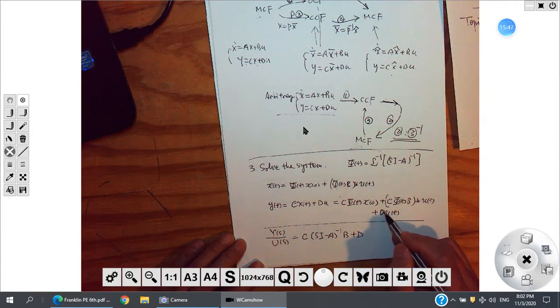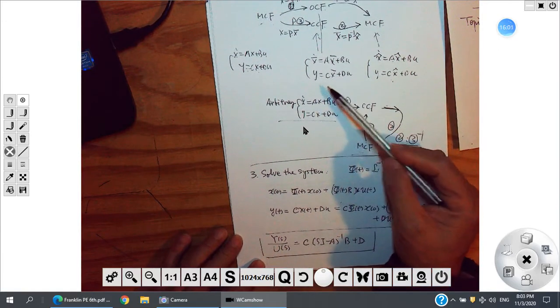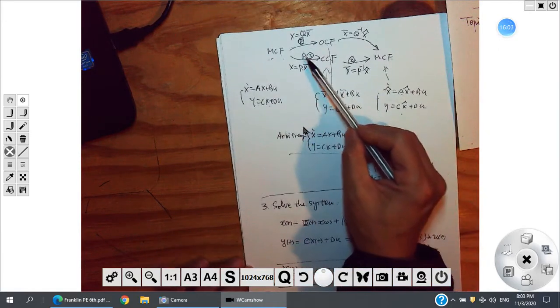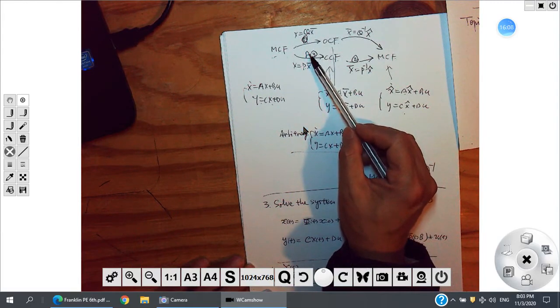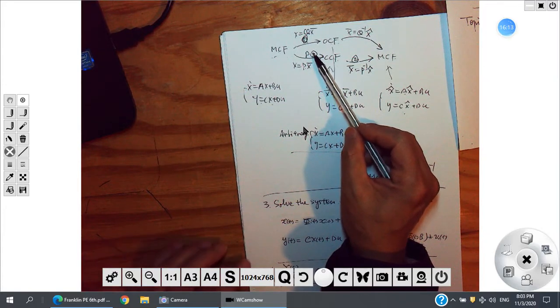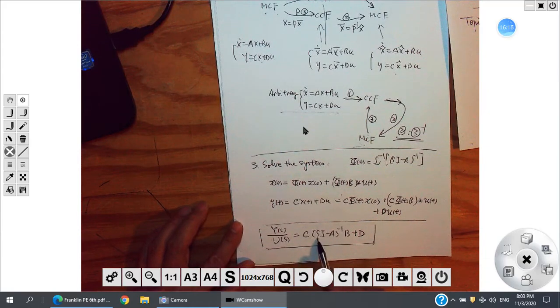Oh, you still have this one. Okay, yeah, something like that. Then plus D. D is here. Now we have transfer function like this. Actually, this one you need in the previous step. In this part, when you try to find this P and Q, you need a matrix M, and for that M you need the transfer function. You need the denominator of the transfer function. Remember? And what is the denominator of the transfer function? It's just this one coming from this inverse.